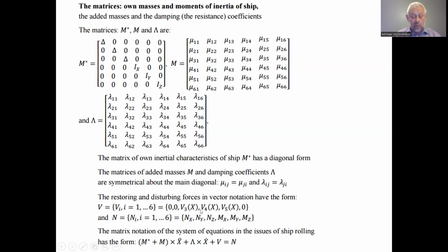So we don't have restoring forces there. We have restoring forces when we consider the vertical rocking of ships, that is the periodic translational motion relative to the applicate axis, vertical, and two rotational motions relative to the longitudinal axis, that is ship heel, and relative to the ordinate axis.